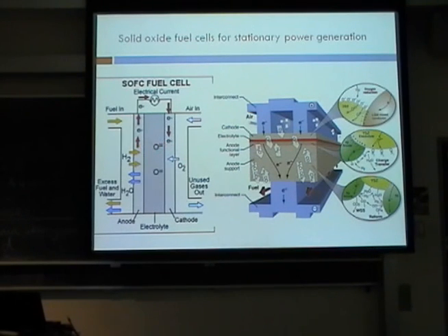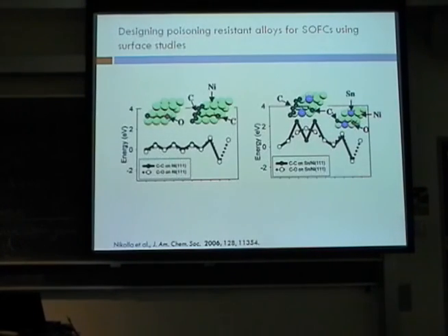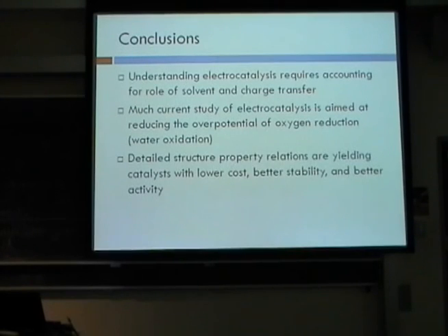You have an oxygen conducting electrode that's usually something like doped yttrium stabilized zirconia, for example. It will conduct oxygen that reacts with the hydrogen to make water. So you have a different species being conducted. You still have electron flow occurring outside the device to provide power. I'll skip that for now.